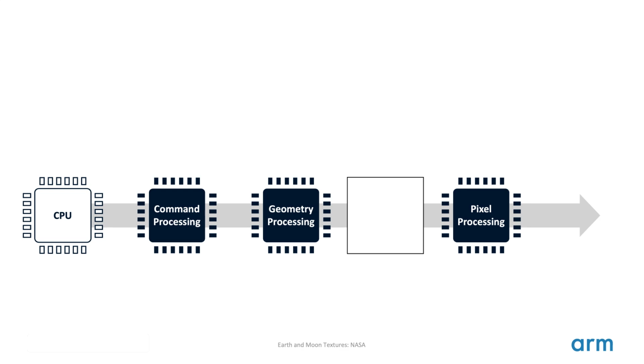There are 4 main stage groups involved. The CPU runs the application and the graphics driver. It is responsible for graphics pre-flight, such as animation and physics, uploading the CPU-generated data into the DRAM, and sending the rendering commands to the GPU. The command processing stage is a control stage inside the GPU, responsible for interpreting the requests made by the CPU and coordinating the GPU's data processing stages.